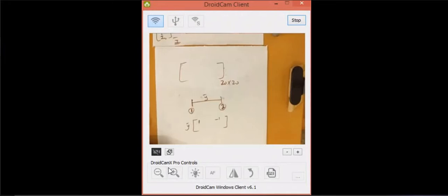And common with others, so it's equal to minus 1. So then for a line connected between 2 buses 1 and 2, for example, the admittance matrix is y equal to the y of the line multiplied by the matrix 1 minus 1, minus 1 1.